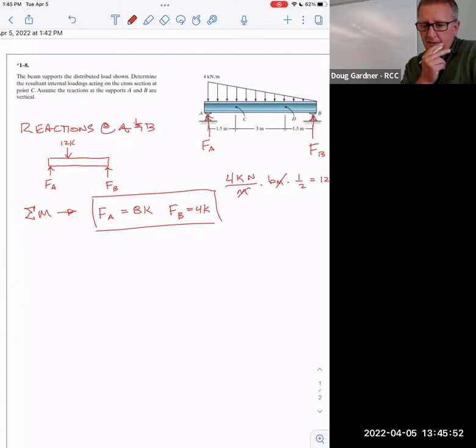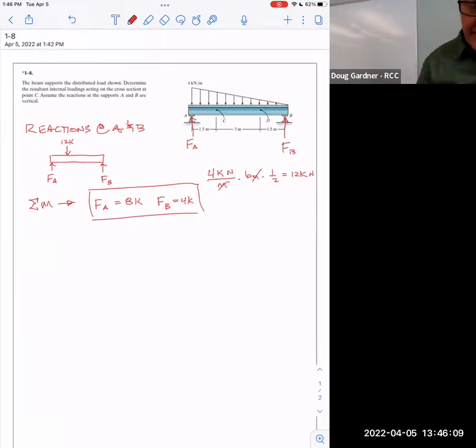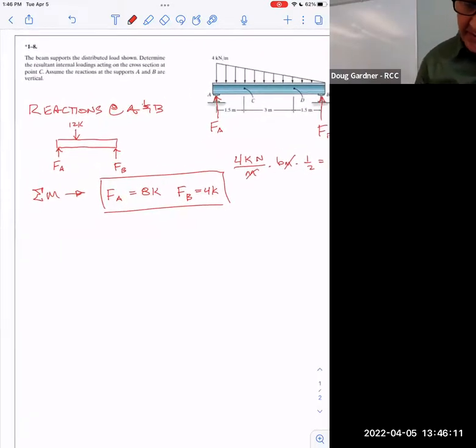Yeah, looks like it's just kind of sitting on top of an I-beam, and if you didn't assume that, there could be a vertical force that would want to push it off. Like if they really were just sitting there, then you better make sure there's no sideways forces or it's going to tip over. Like then you better weld it or bolt it or something like that, right? So I could have not read that and been okay, but let's figure out what C is.